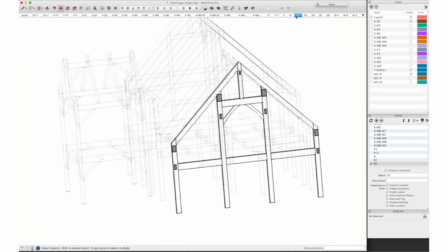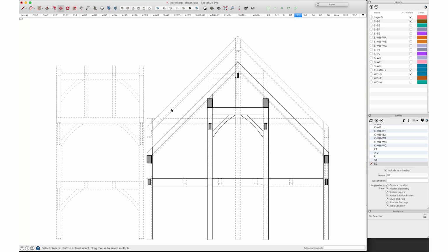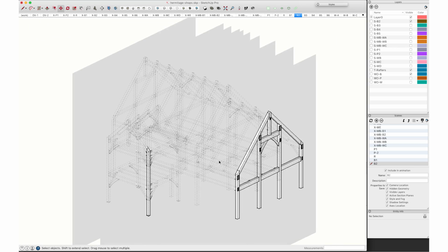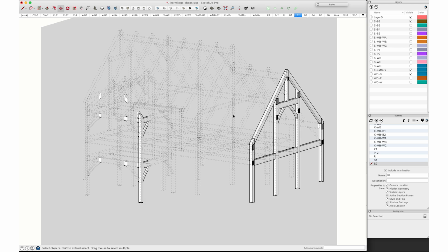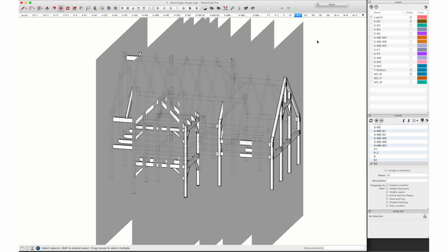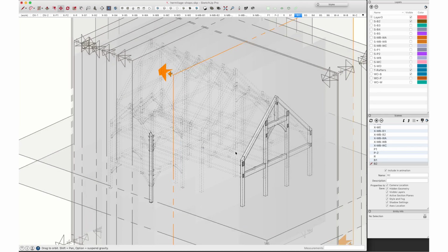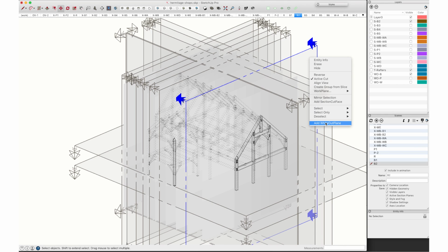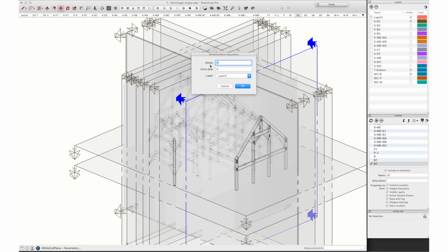I screwed around with trying to use fog. Using the fog in SketchUp, you can kind of blank out what's behind it, and it was always pretty iffy. So a no-brainer is I had a plugin written where you right-click from the section plane, 12 inches behind the section plane, because most of my timbers are 10 inches. Sometimes I have to adjust that. And then 4 feet bigger than the extents of the window. It creates this big white rectangle, and it automatically dumps it on a layer for me, so I don't even have to think about it.